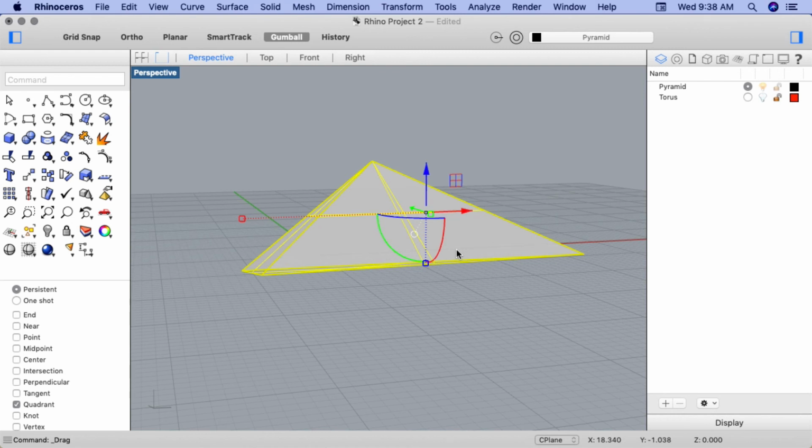Finally, we can press and hold down Shift during scaling to force a 3D constrained scale. For example, I'll hold down Shift and scale along the Z-axis, and note how my whole object scales as well.